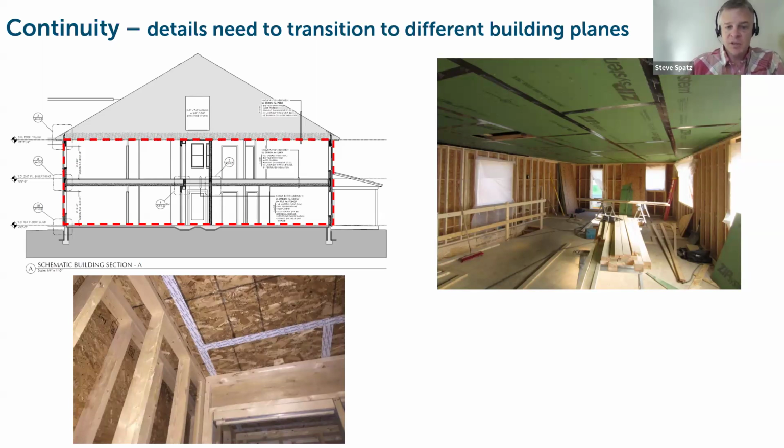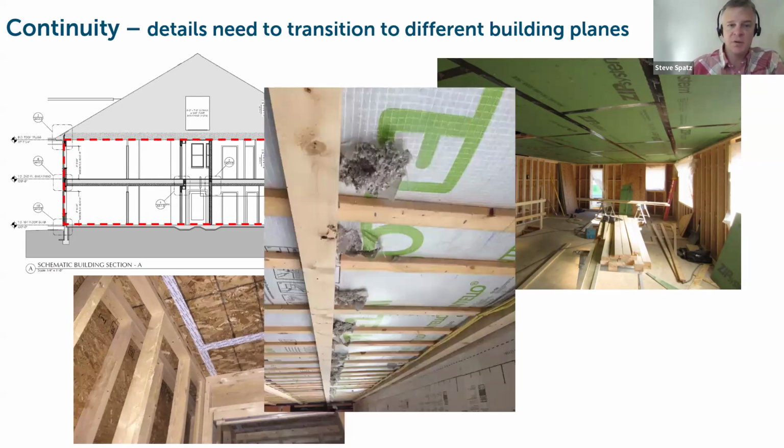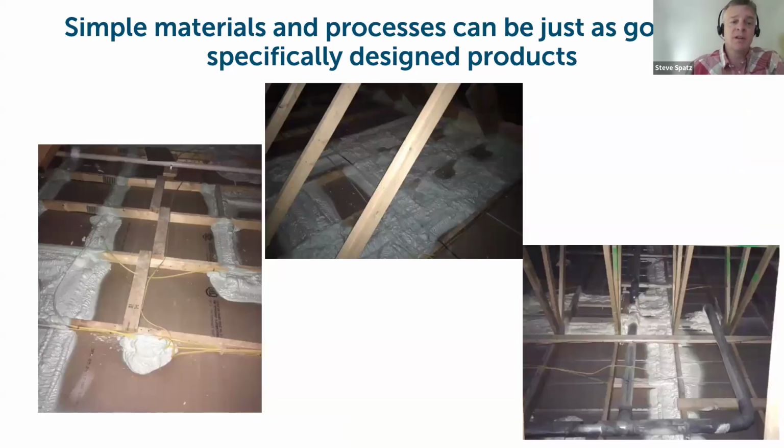You can use sheathing at this layer. You can use a vapor control membrane that is strapped, and then your interior drywall or finishes will go over it. But it doesn't have to be complicated, and it does not have to be a sheathed ceiling plane or even a membrane specifically, depending on the assemblies you're putting together behind that.